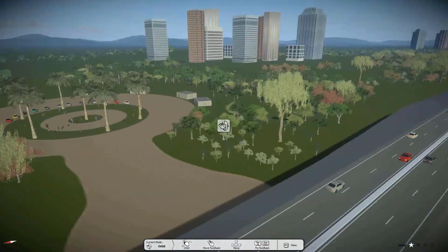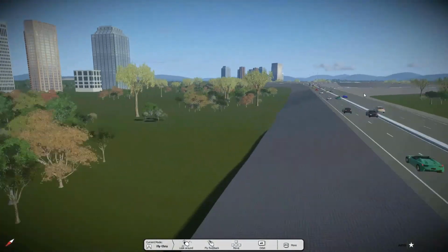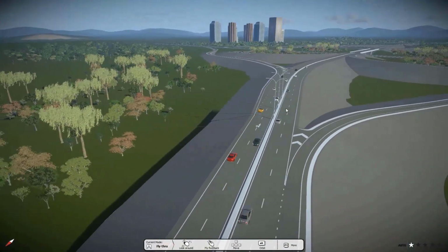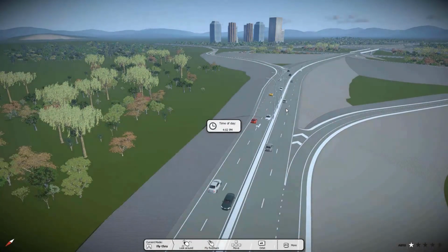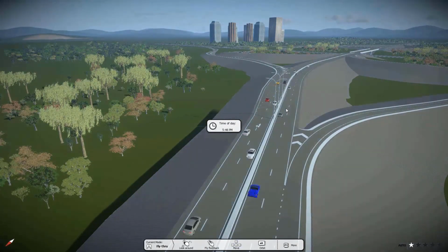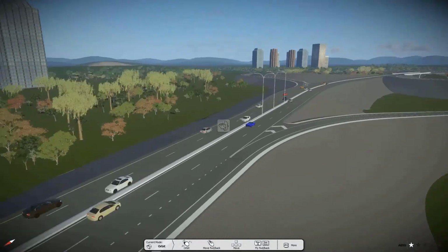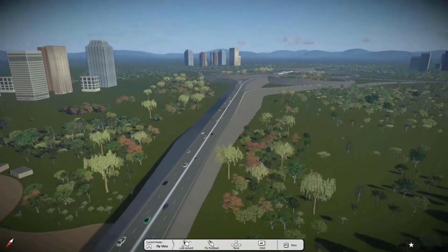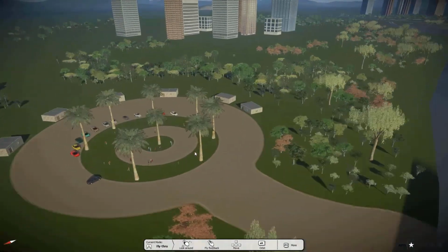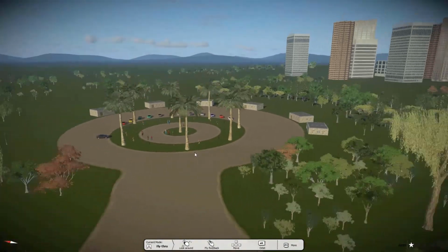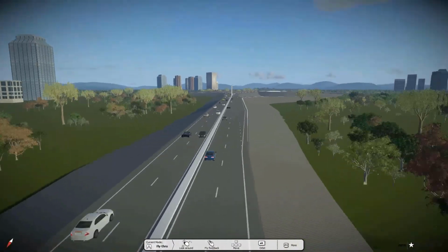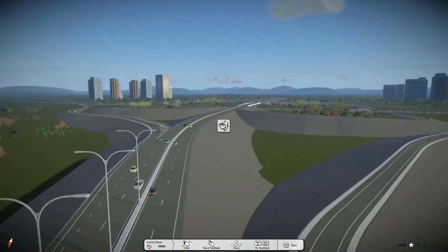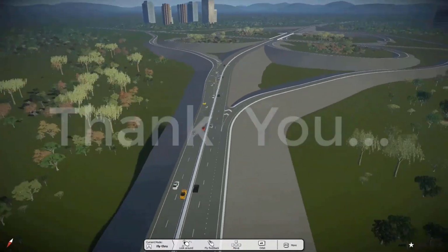You can go anywhere in the published live cube. You can examine any point of view. You can change the daytime by pressing the G key and the H key, and you can switch between walkthrough and fly through mode, and you can share this with anyone. Users cannot edit this. So this is all about LumenRT. I think you liked this session, and if you have any query related to LumenRT, please post it to us.